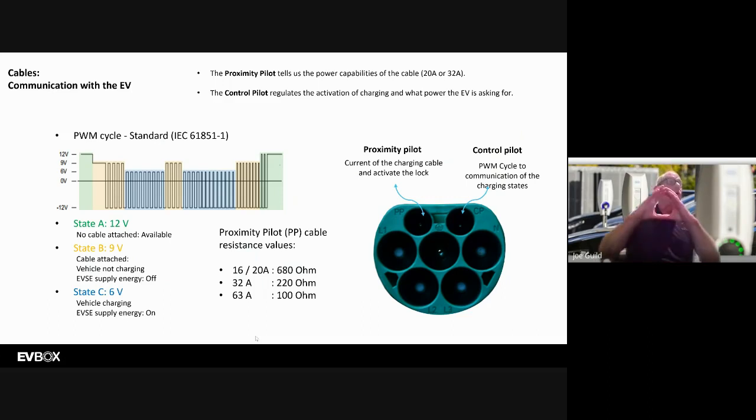And then our LED ring will be blue, charging. That means our relay is closed. Now, it's very, very important because that's the only time that the relay is engaged and that we're charging at full speed. Otherwise, it's only the electronics that are working in the station. So this closes the relay, and of course, as you know, all the checks and balances have to be there, there has to be an authorized rider, there have to be safety mechanisms in place, etc.